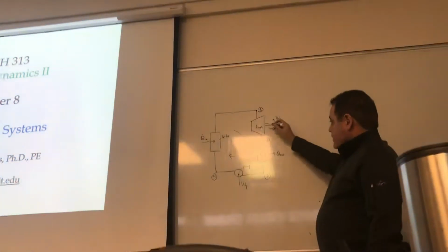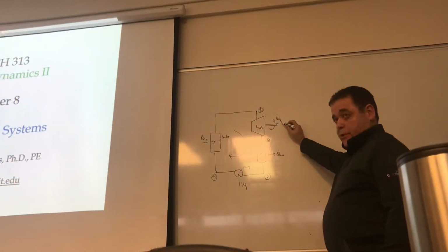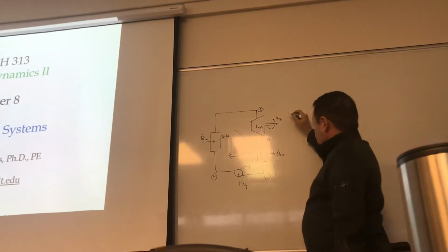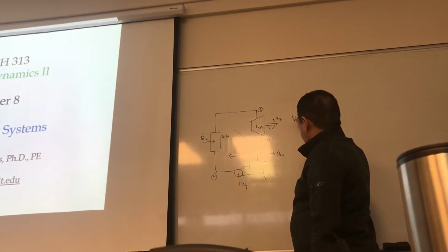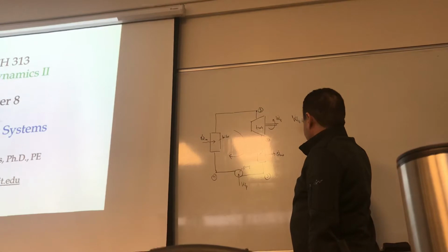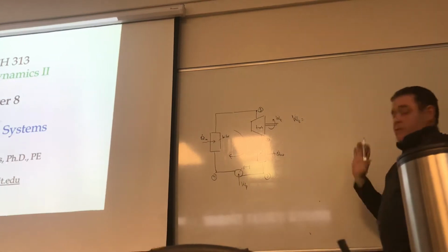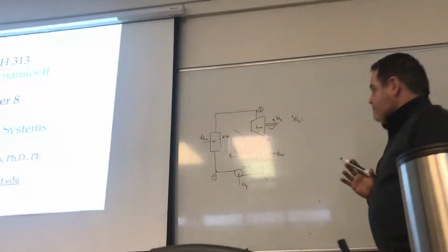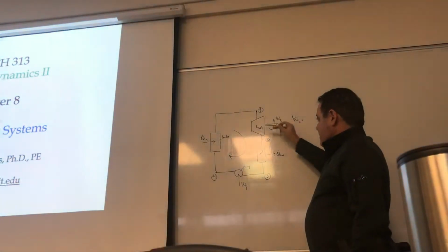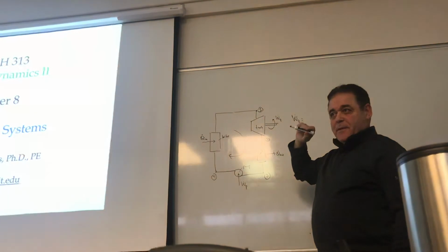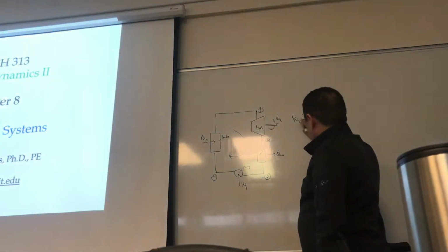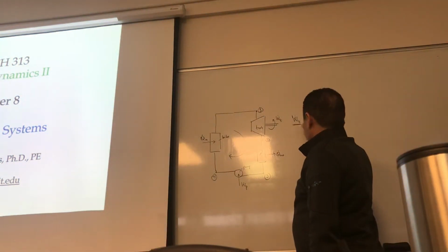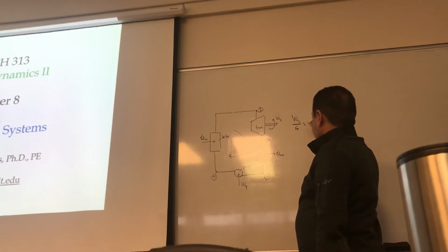Now, the turbine produces work, right? What do you think this work is equal to without looking at your book? Just M dot times H1 minus H2. Yes. So the work per unit mass is equal to H1 minus H2.